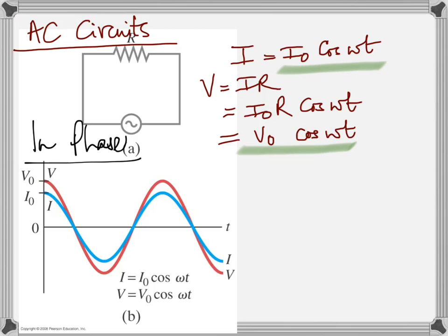Now, on top you have the circuit, and look at this. When the current reaches maximum, exactly at the same time, voltage reaches the maximum, and so on. They both reach zero at the same time, negative maximum at the same time, so they are in phase with each other. That's how the resistance behaves. You'll appreciate this when we look at how an inductor behaves. I hope you got this. Did you get that part? Done. Now let's go to the second one.